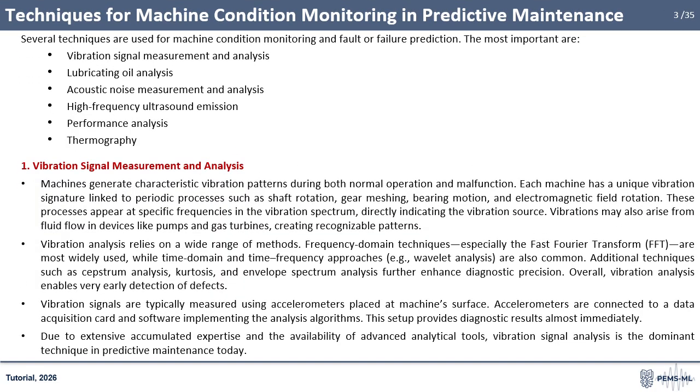Several techniques are used for machine condition monitoring and fault detection, including vibration analysis, lubricating oil analysis, acoustic noise analysis, high-frequency ultrasound emission, performance analysis, and thermography. Among these, vibration analysis is the most widely used.